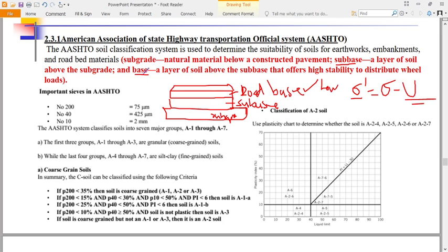This material, with the sub-base material, should sometimes have the ability to drain water. So it can be designed as a filter layer or as a construction work platform, depending on the requirement of the layer. If it's near waterlogged places, it can be designed as a drainage layer. It should be fine enough to prevent ingress of material from the subgrade, but also coarse enough to allow water to drain through it.